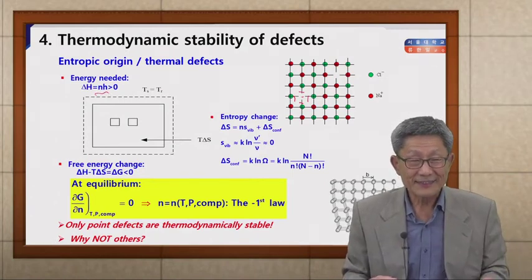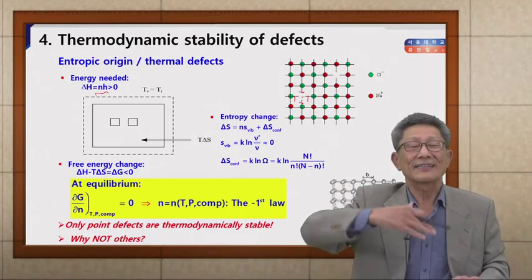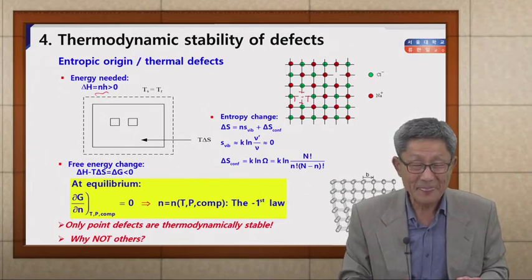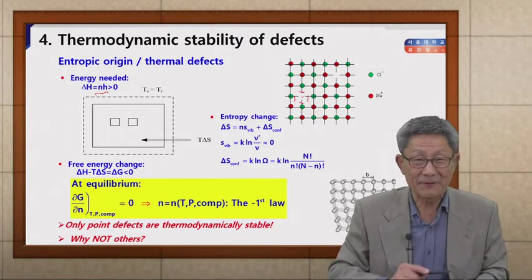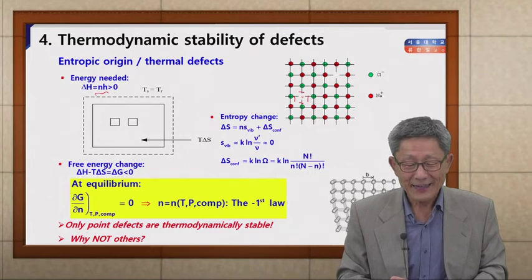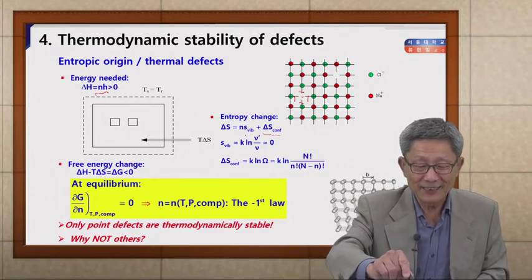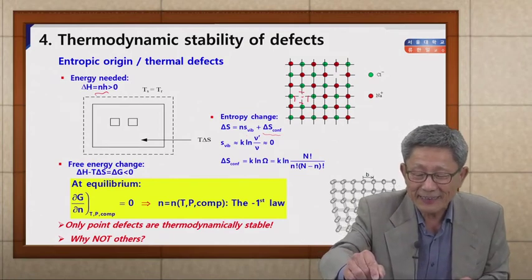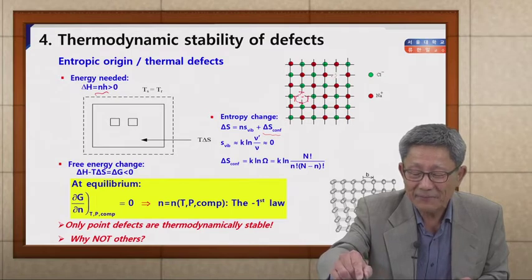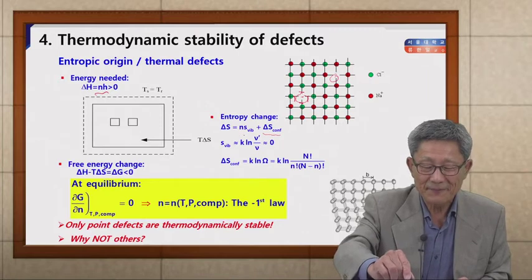As a consequence, the energy of your overall system has increased. Oh, it is prohibited in thermodynamics, right? But by making this kind of point defect, you are increasing the configurational entropy, in addition to the small vibrational entropy generated by making one point defect. Let me tell you the origin of this vibration frequency.